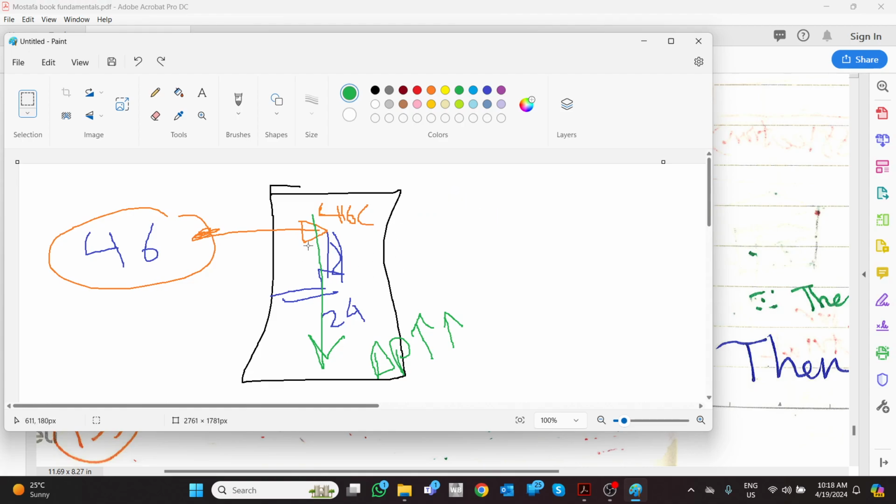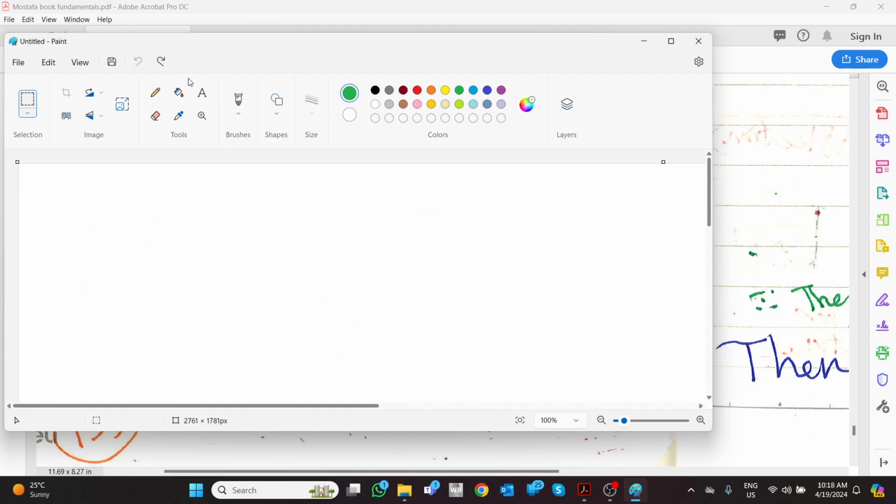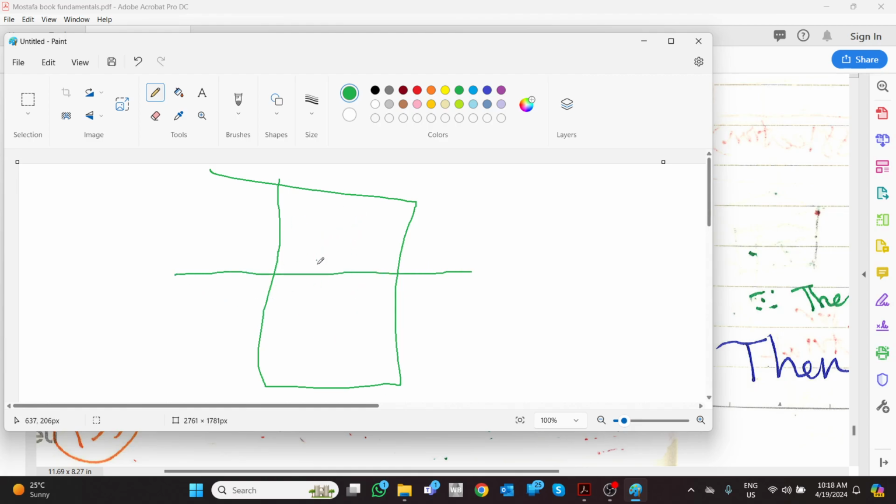See, in case you have a stack effect, normally you will have high pressure in one place and low pressure in another, or the opposite case, but you will have one line where the pressure is going to be equal, because it goes from low to high. So where is the median line? It will be here. Approximately it is from 1/3 to 1/2 of the total height.